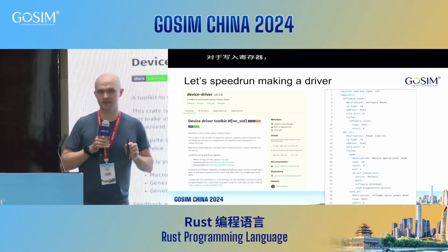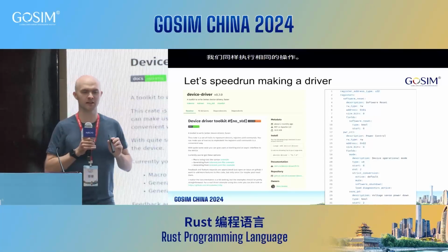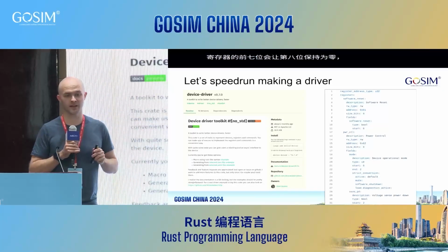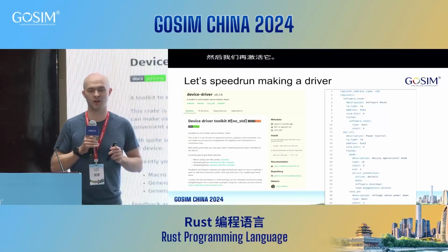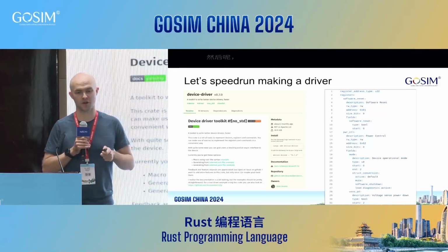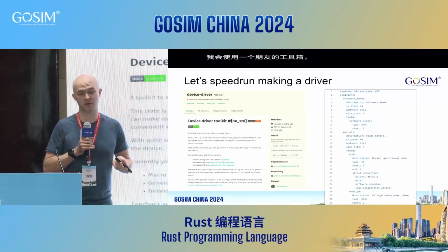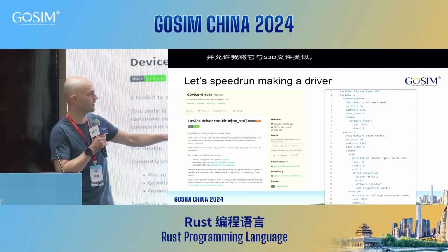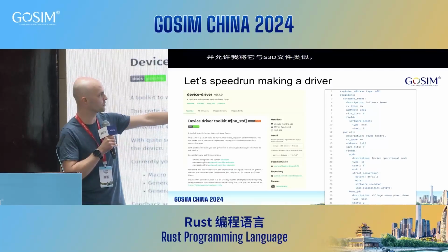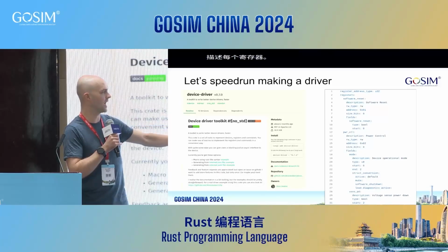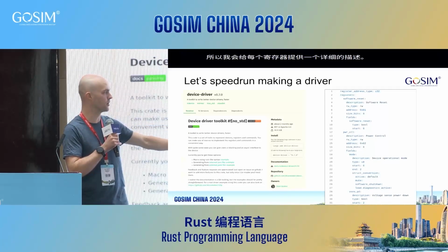And then I'll use a crate from a friend of mine, a device driver. Dion made this, and it allows me to, similar to an SVD file, make a YAML file, which describes each register. So I'll give a nice description to each register. I'll say what each bit means, and I can even define, for example, for the power control register, the field called mode, and it has the values active, mute, software shutdown, and load diagnostics active.